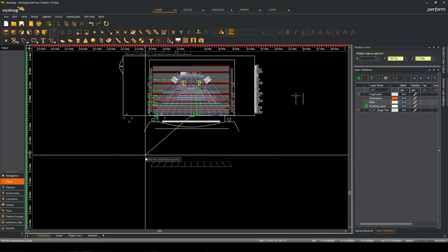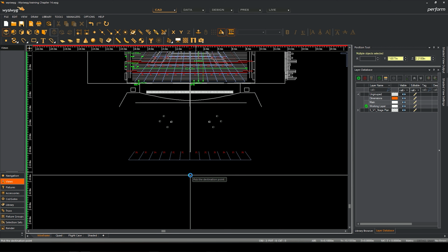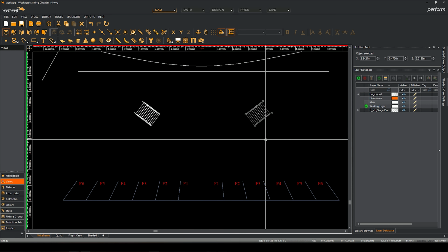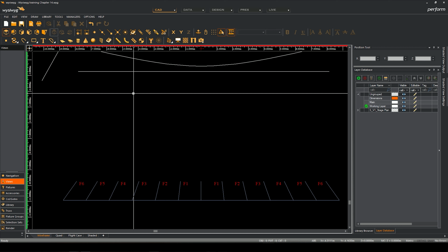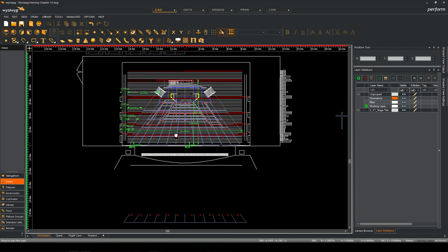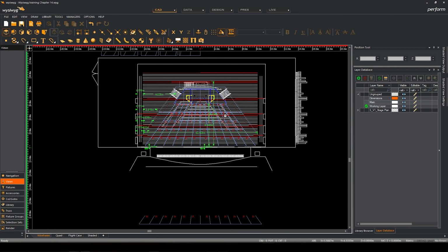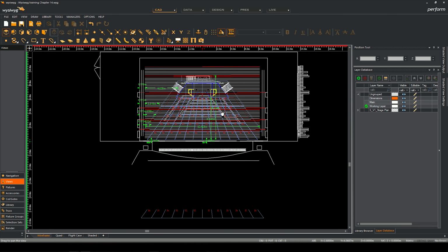Click Add, and you can see I've got these two little things here that become the stairs. So I'll just click and place them there. And that's a way of quickly inserting things. So if you've got an object in a plan that you use a lot, we can create insertables. And you can save those into your Wysiwyg folder. Wysiwyg has like a template folder that you can save to.